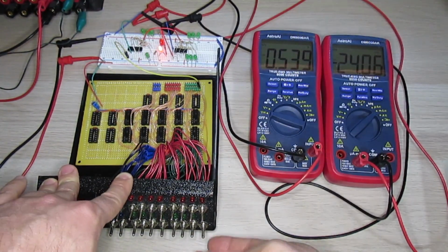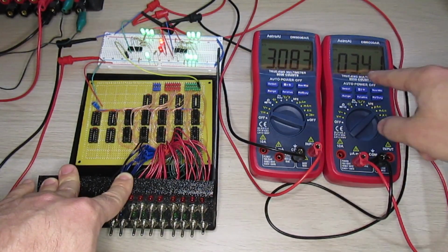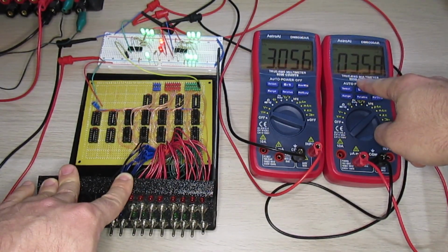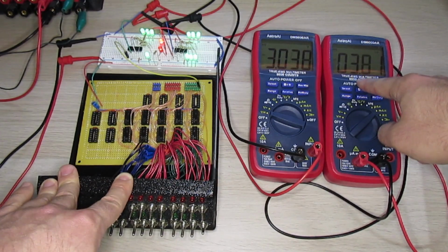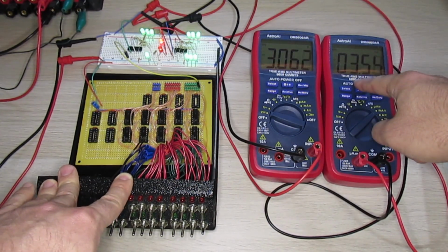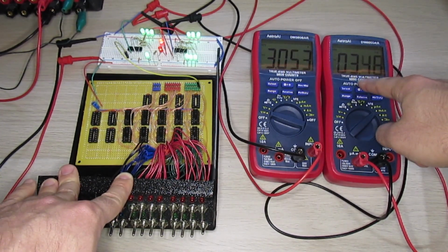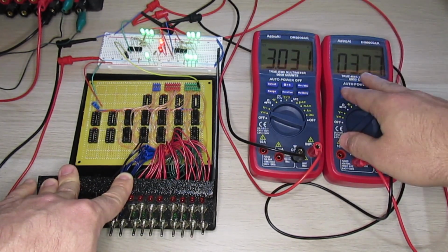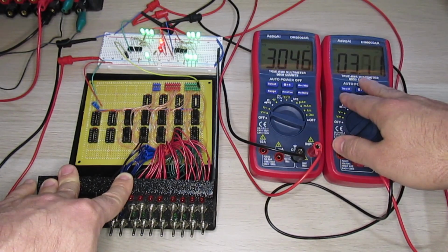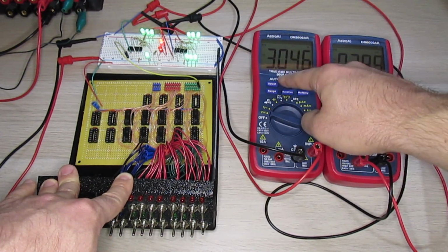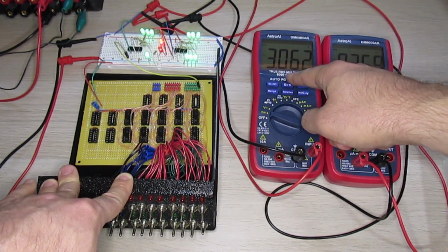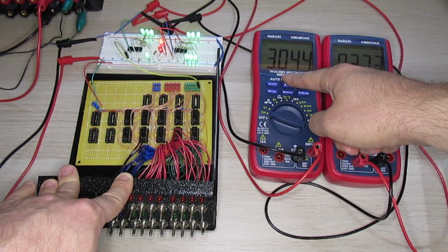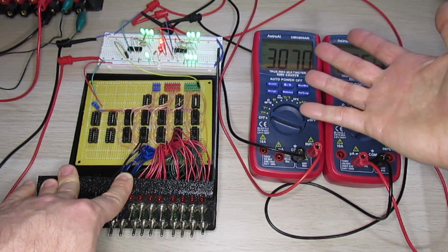And then in the output high state, we see that we're drawing about 3.5 milliamps, maybe a bit more, which is way above the 0.4 milliamps that the datasheet is asking us to draw in the output high state. So this is way out there. This is almost 10 times as much as the datasheet is asking us to draw from the output. And the voltage has gone all the way down to 3 volts, but that's still above the 2.4 volts that the datasheet promises, so everything's still happy there.